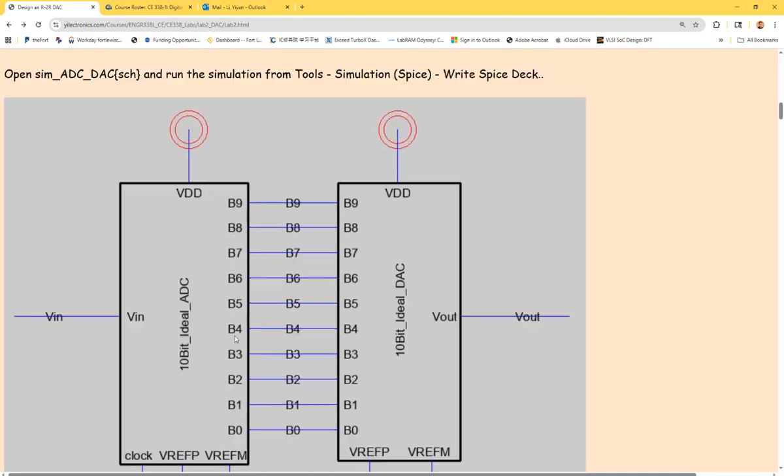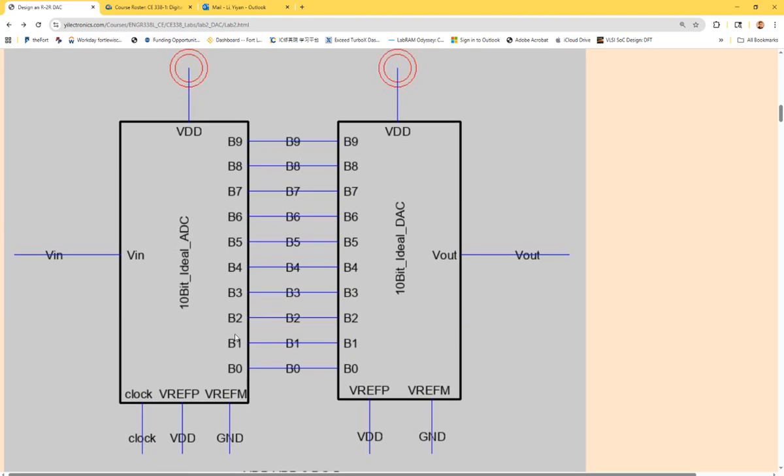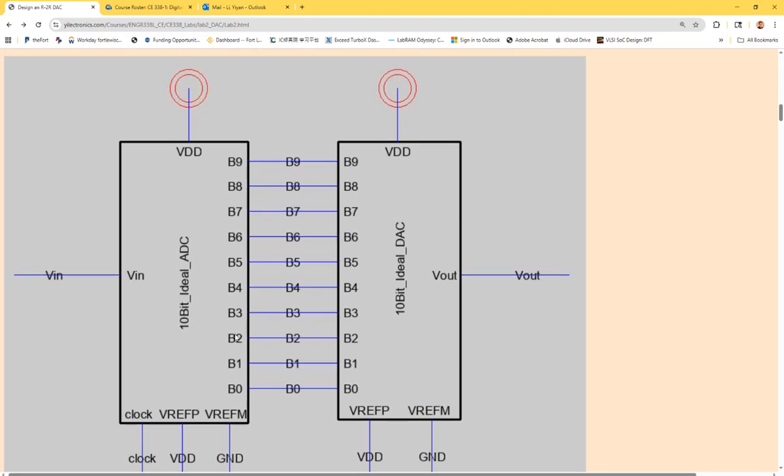One thing it didn't tell you, but you need to know, is that if you grab a circle symbol from the library, you can directly drag and drop it into your schematic view. This thing doesn't have a name with it, but it's called VDD. It's just VDD. It's a global variable, which means if you put a VDD in this layer and wrap it with another layer or 10 more layers, it doesn't matter. This global port will be reported to the upper layer as well.